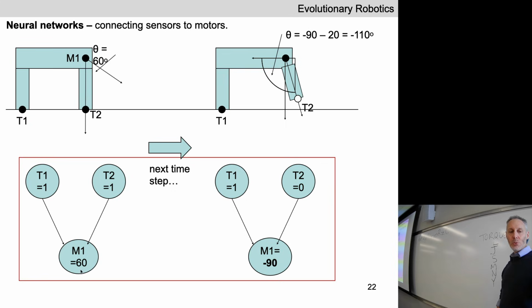We just saw how this works through the code snippet. So the desired angle of the joint is 60. That goes into the physics engine. The physics engine applies a force to the front leg. The front leg starts to extend outward. And the moment it does, at the next time step, no matter how much it rotates forward, by rotating forward, it pulls the front leg off the ground, which means that the touch sensor inside the front leg stops firing.